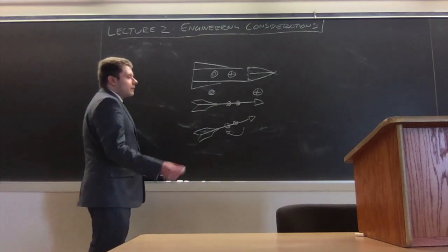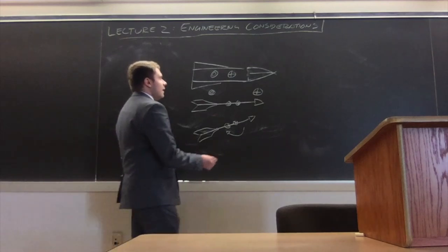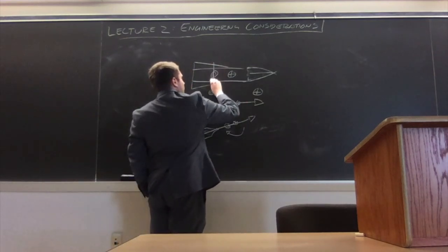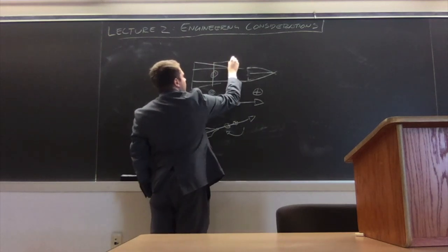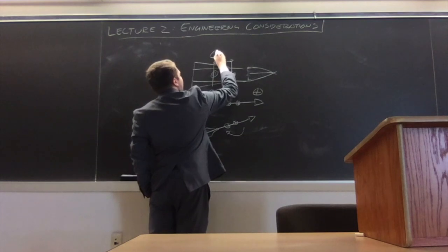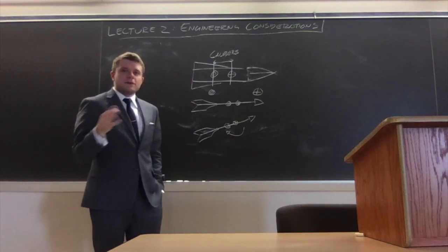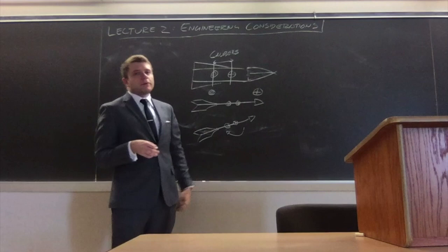Now, of course, that is a very general case thing, but there are some specific considerations to make. When we talk about high-power rockets, which is what I have a lot of background in, we talk about the calibers of stability. And that is the distance between the center of gravity and the center of pressure divided by the diameter of the rocket.